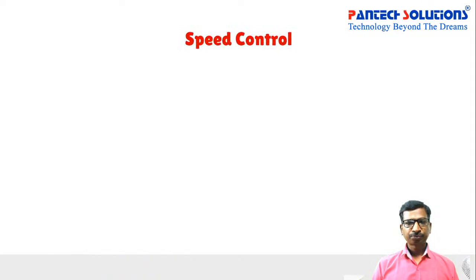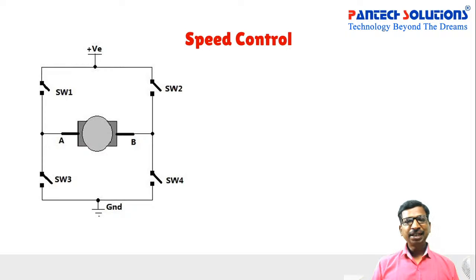And for understanding the speed control, we have a power converter called the H-bridge converter. In the H-bridge converter, you can get four terminals. One is the positive and negative, and another one is terminal A and terminal B. And it has four switches.